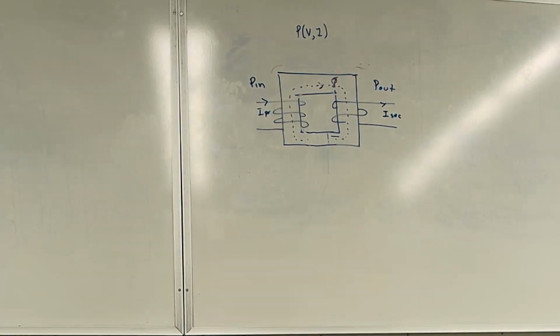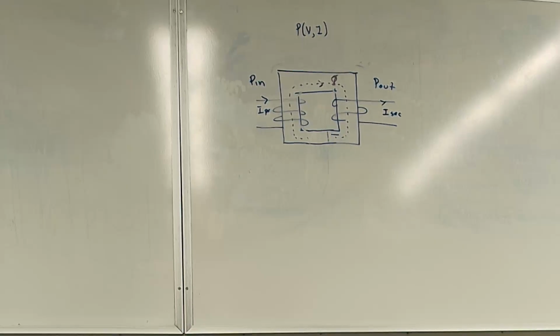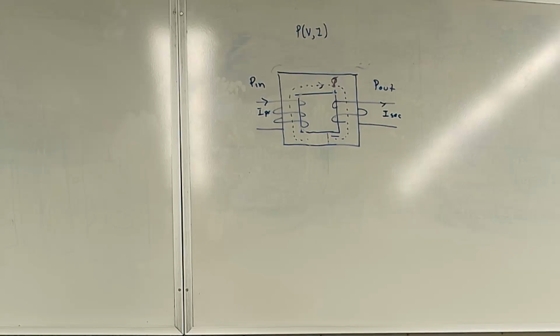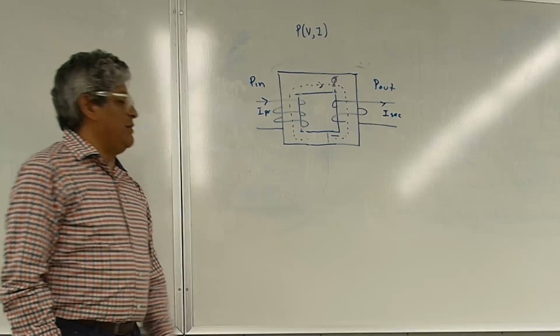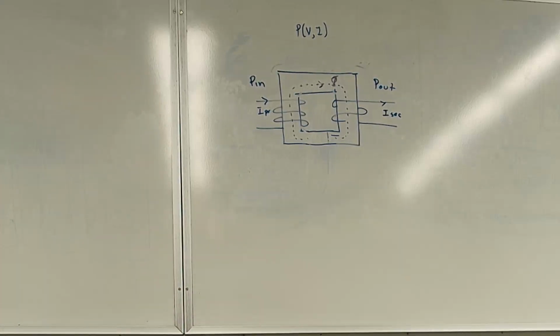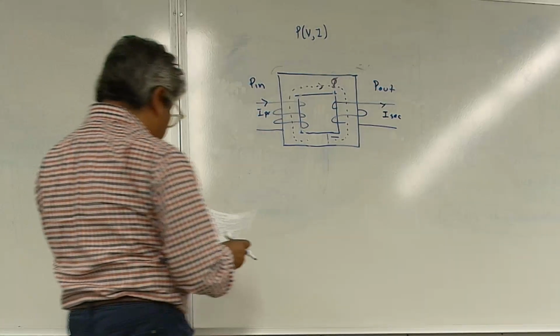And they do testing under different loading conditions, and they're monitoring that. If you go work for Edison, in the apparatus group, you learn this. When they do the testing, the way they capture that information with the manufacturers is in dollars. How much is it costing today in losses, right? So they have a table where they say, this is how much it's costing. So not being able to maintain the flux inside the core is a big deal. And the larger the transformer, the bigger the deal.